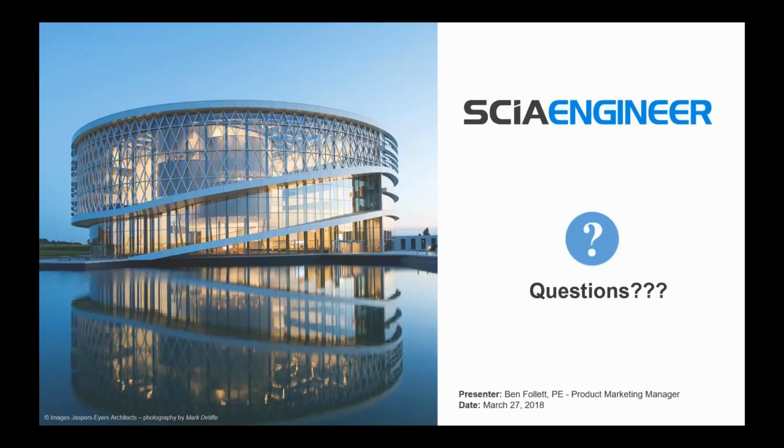We don't have design checks on the plates themselves. One of the things that we do have, and we've seen some of our customers do, is a solution which we call SCIA design forms. Essentially, it's a scripting environment that allows you to create your own checks and attach them to the software. Imagine a MathCAD-like interface where you could do some very brief programming. You could pull results and information from the model to help create that check, and then you just establish the check within the interface.